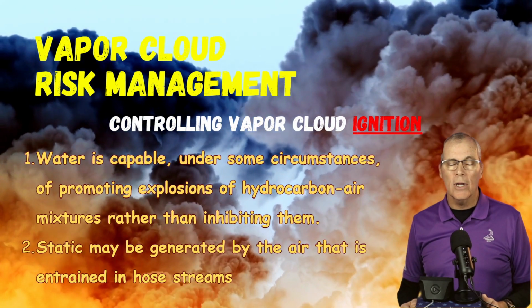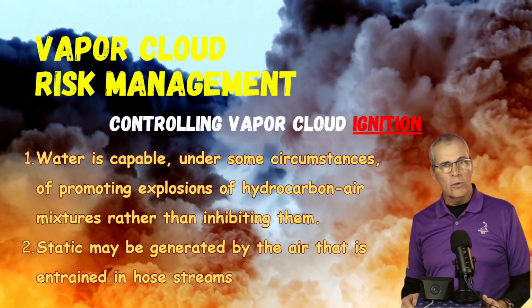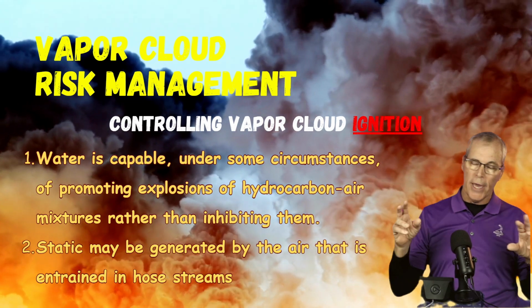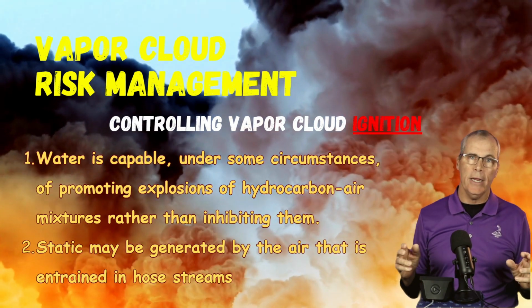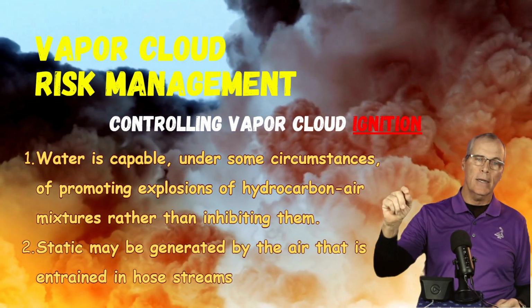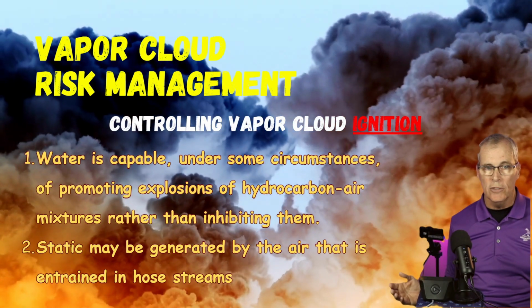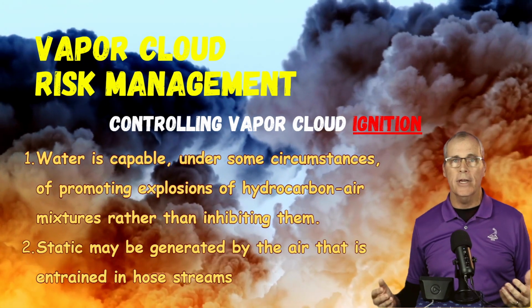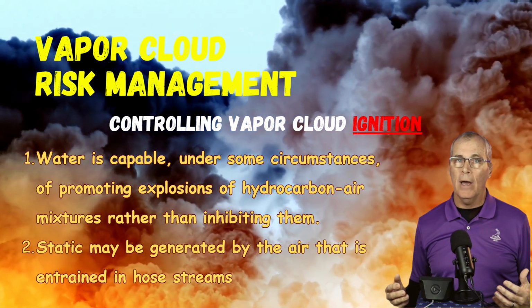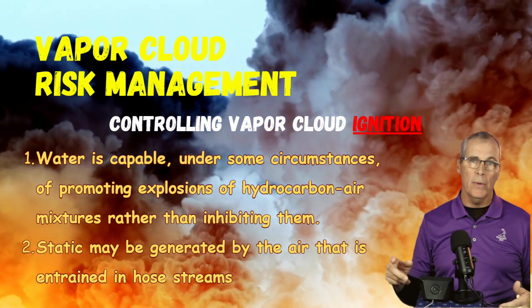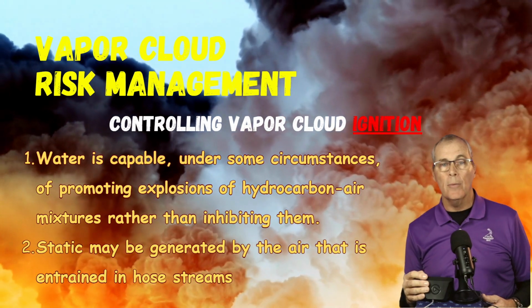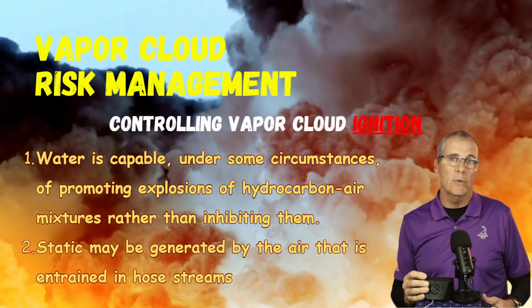All right, now be real careful about ignition. When you're using water and moving air, air can build up static. And yes, that static can ignite the cloud rather than move it or control it. So it's a judgment thing. If the air is very dry, if you're already getting shocked, be very careful about how you apply that water up into that vapor cloud, because it could contribute to an ignition.